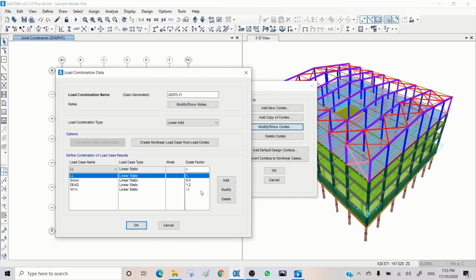So you have different wind pressure here. So if you put it -1, that means you simply reverse it. But now this is windward, so the load here is different from leeward, but currently you apply just leeward here in this load pattern. So it is not correct. It's not that simple, just about windward and leeward, because you have a combination of different wind loads on elements.